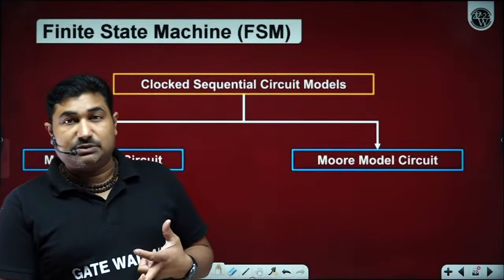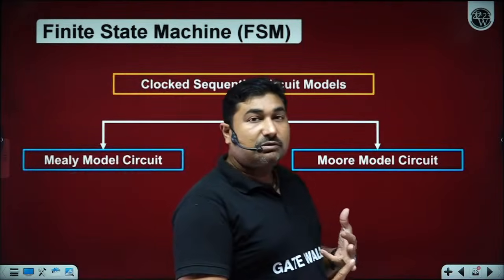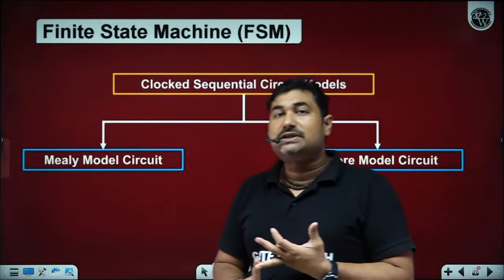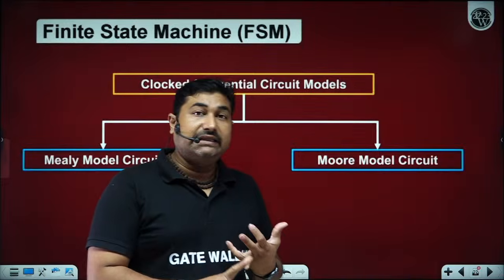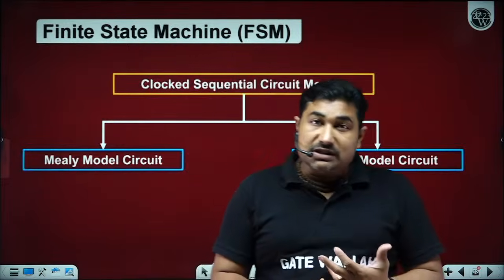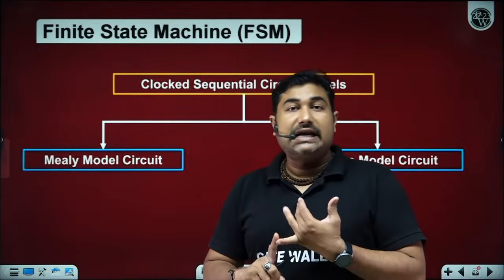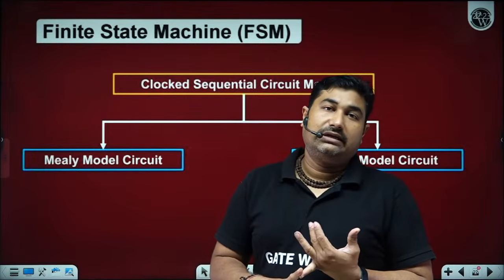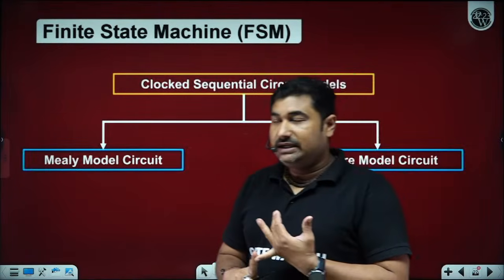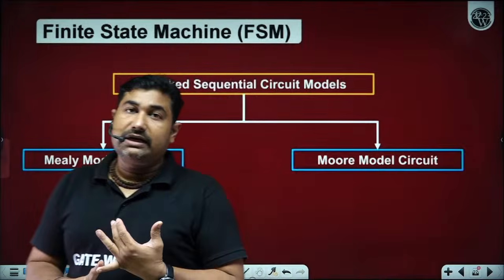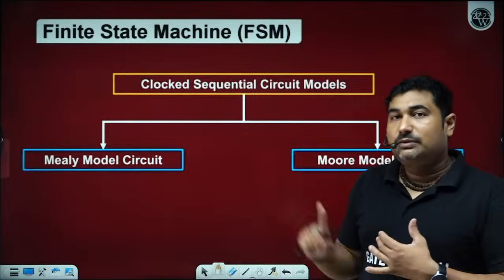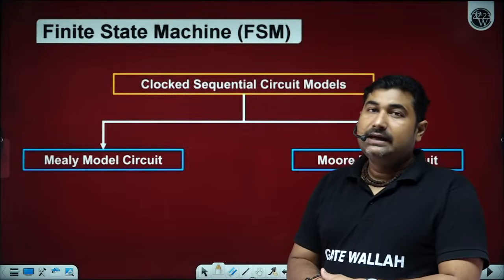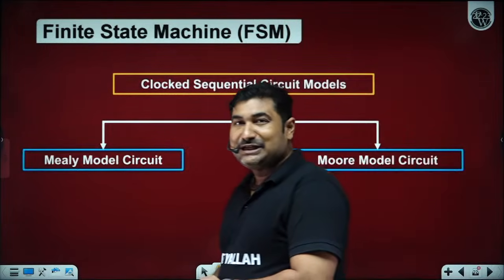We know the steps to design a desired synchronous counter, synchronous series or parallel carry up, synchronous series or parallel carry down counter, time period of the clock needed, why they are faster compared to the asynchronous counter, and also we have observed ring counter and Johnson ring counter. And we have seen lockout may occur in the Johnson ring counter. So these are the important things that you have to remember up to the lecture completed.